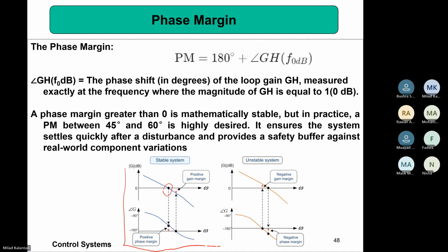You will see from this Bode diagram that the phase has not reached even 100 degrees yet. And then the distance of this phase to 180 degrees basically says how stable your system is.